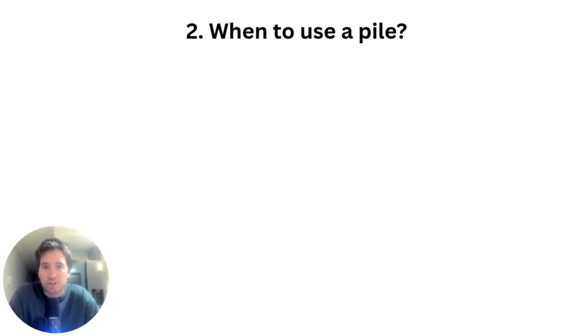So a typical question is when to actually use a pile. If we're looking at shallow foundations or deep foundations, as a rule of thumb, you should typically just always try to go for a shallow foundation first because they're cheaper. You don't need to bring out a piling rig on site, and it's easier to get a larger surface area with strip footings, pad footings, and raft footings.